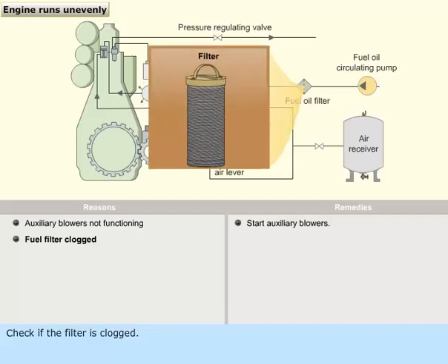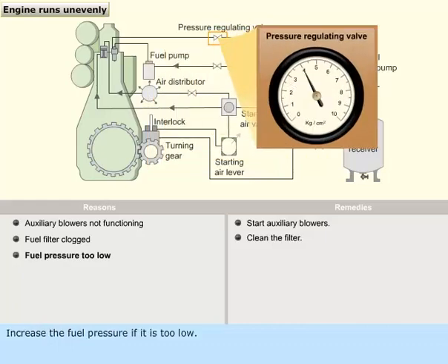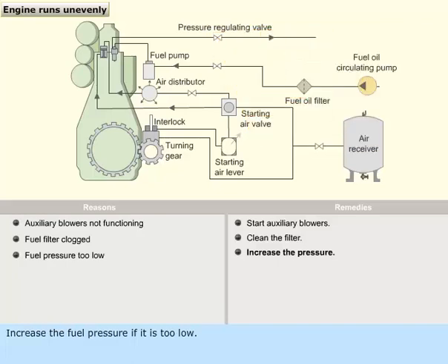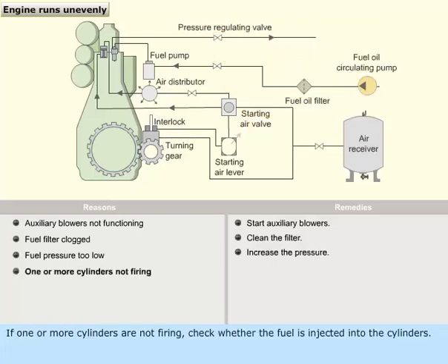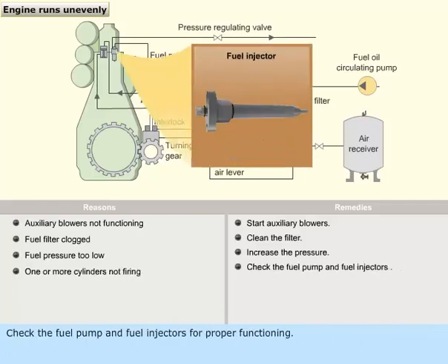Check if the filter is clogged. Clean the filter. Increase the fuel pressure if it is too low. If one or more cylinders are not firing, check whether the fuel is injected into the cylinders. Check the fuel pump and fuel injectors for proper functioning.